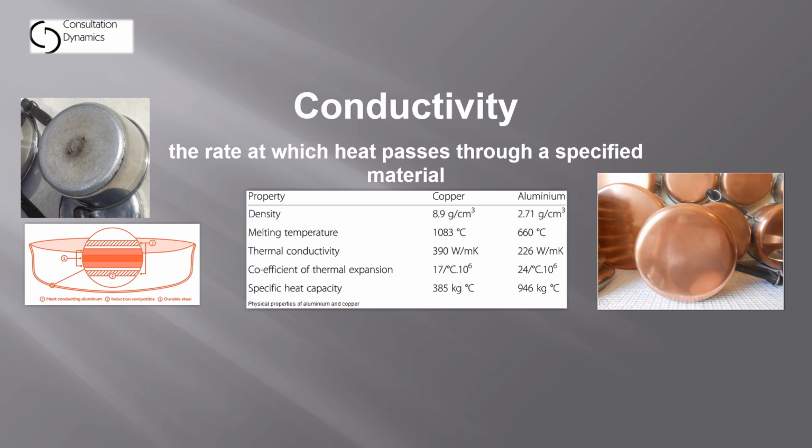And the reason for this is that in its raw state, if you were to just do stainless steel cookware, the only part of the pan that would heat up would be right in the very center. It wouldn't spread out to the edges of the pan or the pot that you're cooking in. And so the entire bottom of the stainless steel is then clad with aluminum or copper in order to get the heat to radiate all the way to the edges and get good even cooking along the bottom.